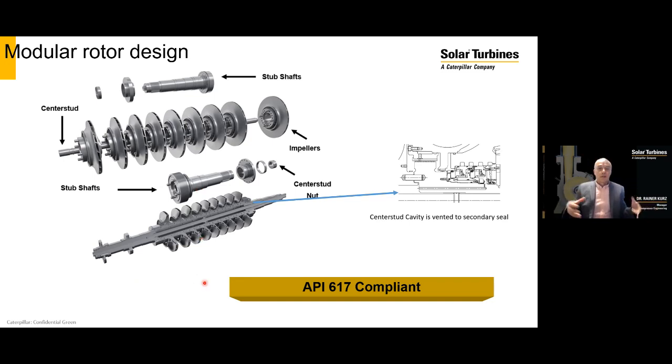So the reason why we're doing that is that this design makes restaging the machine, when after many years of service the operating conditions change to the point that it's advantageous to modify the aerodynamics, very fast and very economically attractive.